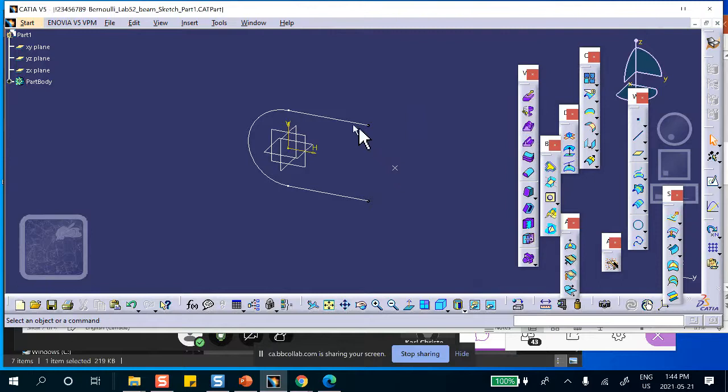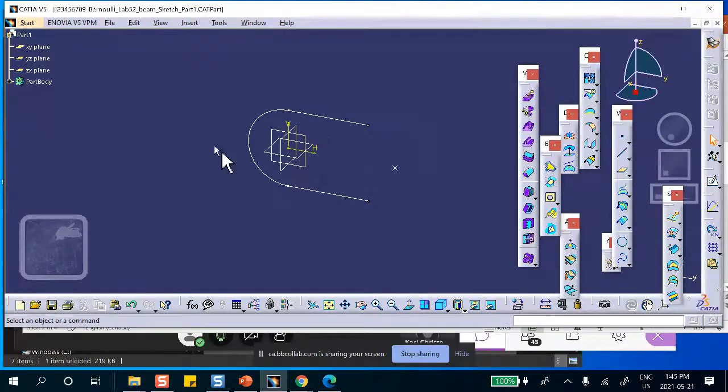And this point right now is in that plane. So when you drop a perpendicular to that plane, it's going to be something like this. This is the y direction. X is always along the beam, and Z is perpendicular to both. The moral of the story is that the XYZ talked about in the orientation point is not the global XYZ.